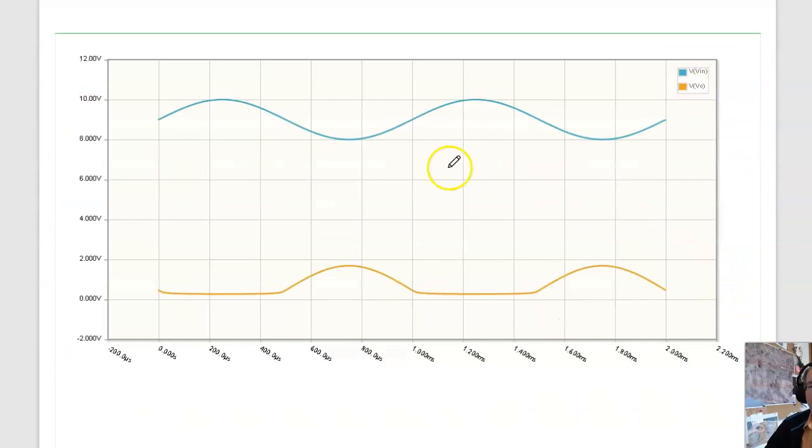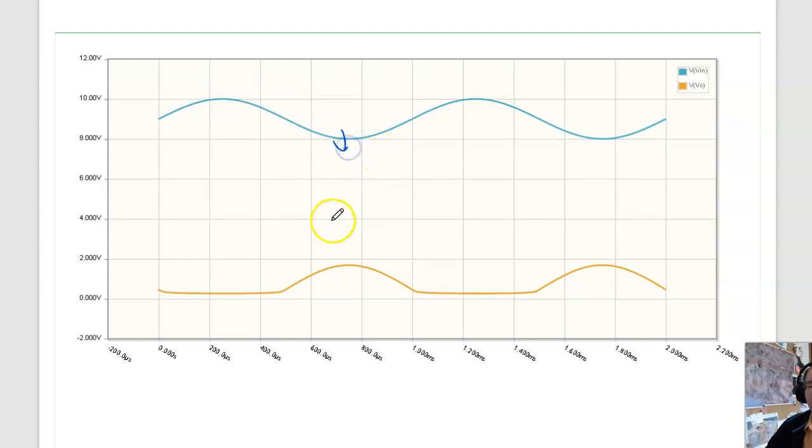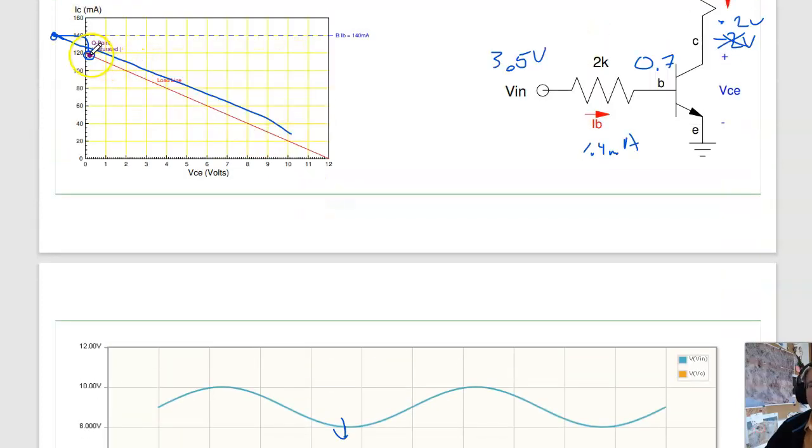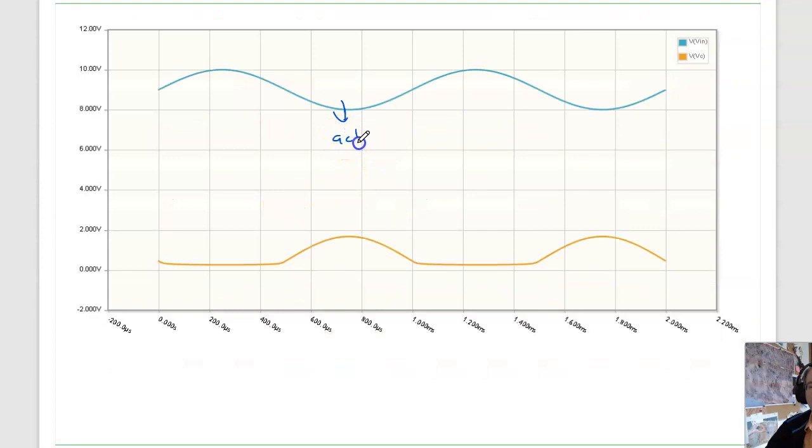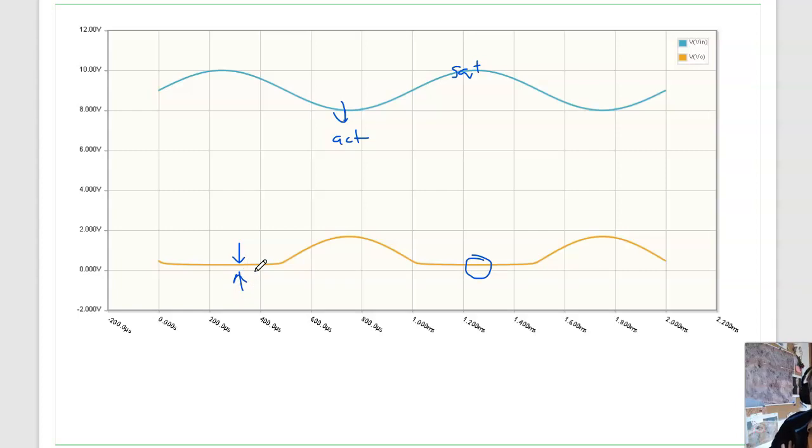And in CircuitLab, you can see that. If I take the input voltage and apply a DC offset, if it gets too large, I'm going to saturate the transistor. As the voltage comes down, I enter the active region. As it comes down, I go from here, left, into the active region. The voltage drops. So right here, I'm active. All the rest, when the voltage is clipping, that's saturated. And you kind of see the voltage collector to emitter, that's this distance right here. We're assuming it's 0.2 volts. It's close to 0, but not quite 0. So we say 0.2, it'll actually be like 0.1, 0.15, 0.25, somewhere in that ballpark.